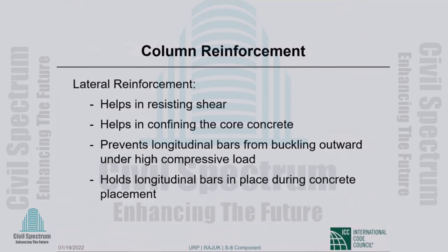Lateral reinforcement plays very, very important roles in a column. First of all, it resists shear. So the lateral reinforcement is also shear reinforcement. In a beam, the shear reinforcement is vertical. In a column, the shear reinforcement is horizontal.